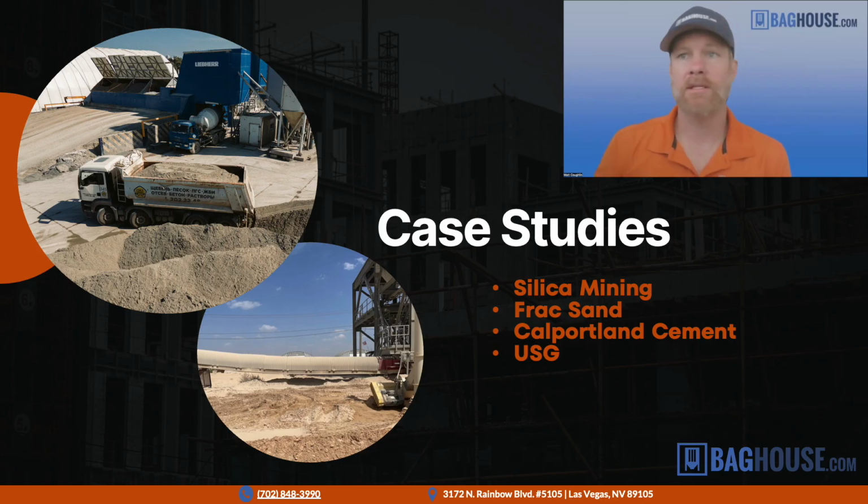So although the system might have been designed properly 15 years ago, now there are holes worn in the duct elbows from the abrasive dust, and holes worn in the housings of the dust collectors, so they're having performance issues. So what we did is we walked through the entire system for each of these, and documented where you're losing your airflow and suction to these holes and degradation.